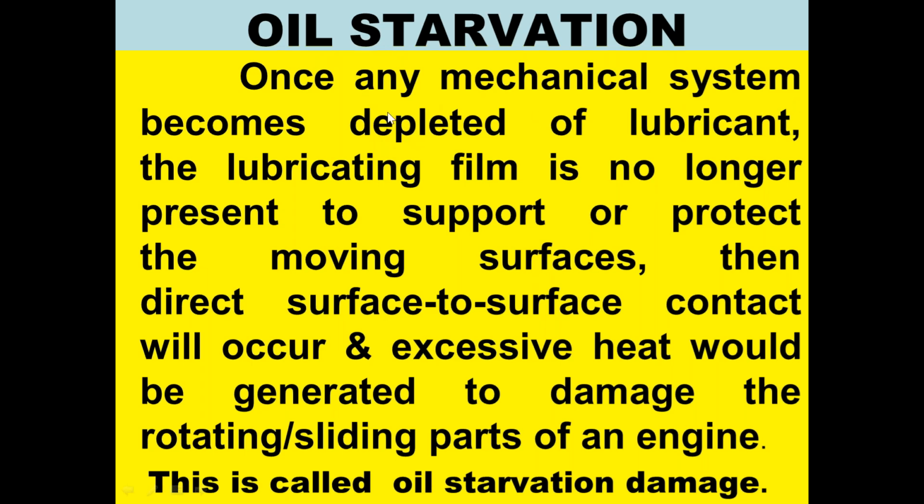Once any mechanical system becomes depleted of lubricant, the lubricant film is no longer present to support or protect the moving surfaces. Then direct surface to surface contact will occur, and excessive heat would be generated to damage the rotating and sliding parts of an engine. This is called oil starvation damage.